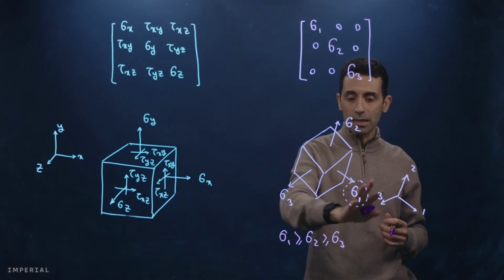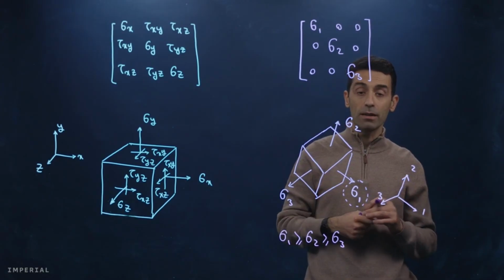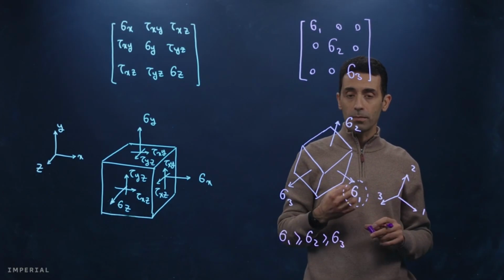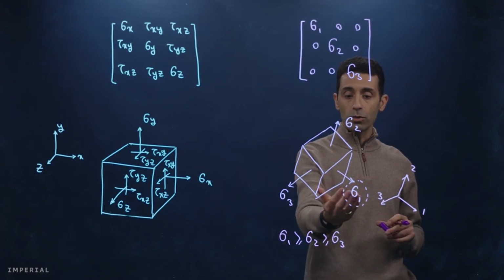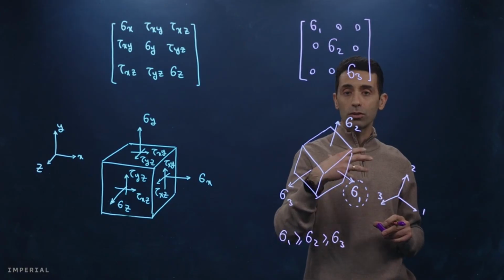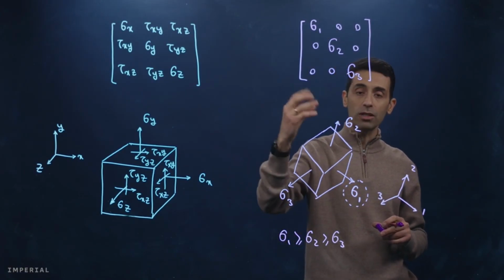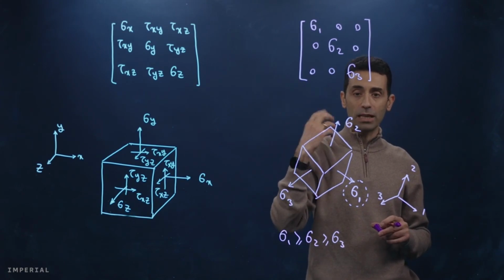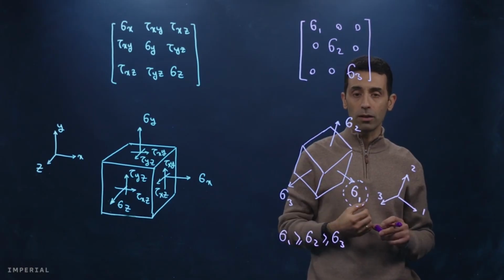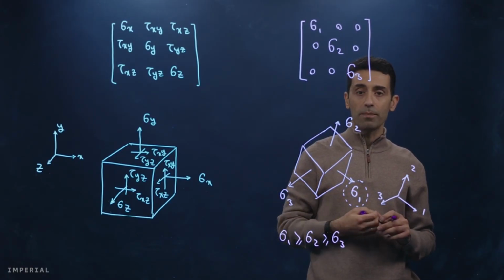You will see that this is a useful definition when we are looking at failure criteria. For instance, for brittle material, most of the time we use this tensile normal stress in order to decide whether the stress state has reached a magnitude and intensity that failure would occur in our brittle material, and we call that one the maximum principal stress criterion.